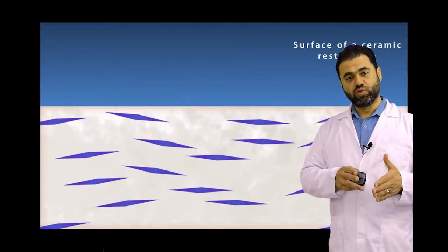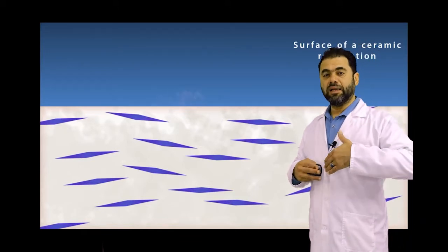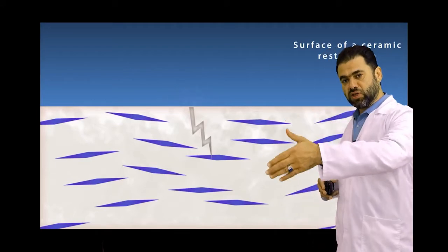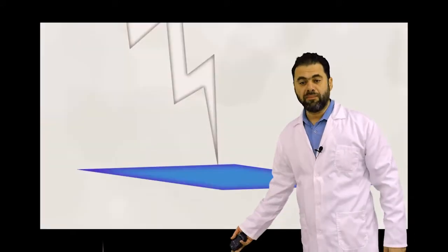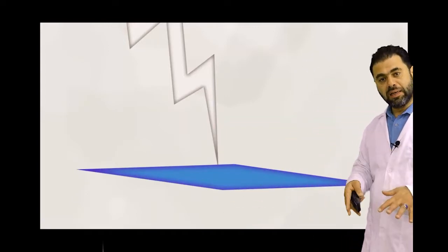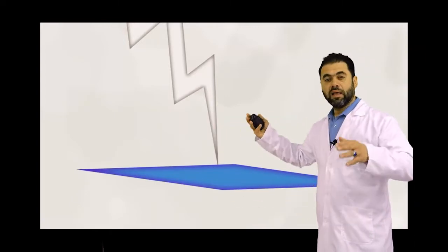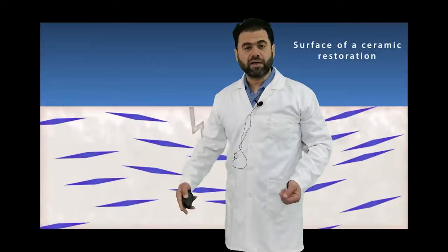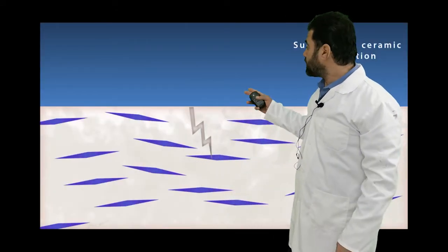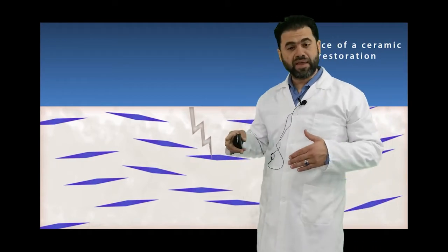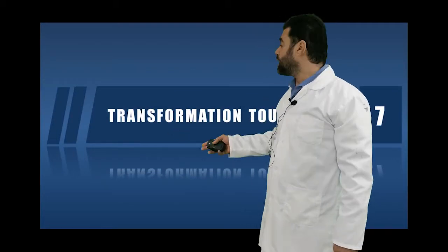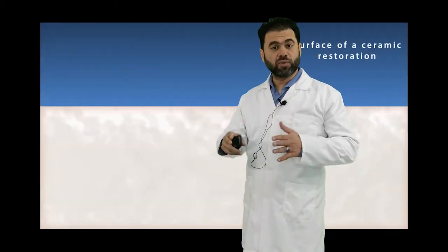The crack is there, but we don't want it to develop, so we want to do a disruption, to disrupt the crack propagation so it doesn't move forward. So we put materials inside the ceramic that prevent the crack from passing through. These materials, like alumina and zirconia, when the crack propagates within the ceramic and reaches this stronger material, it cannot pass through it, so it will stop there.